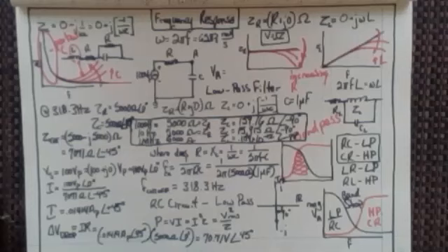Now we could break that up too. You're probably thinking to yourself, well, I can already see that at 45 degrees, if I wanted to turn this back into a complex number, rectilinear, a plus jb notation, that I really only have to multiply 70.71 times the cosine of 45 degrees, which, by the way, is 0.7071. So 0.7071 of 70, doesn't that give me 50? That's right. 50 volts plus J 50 volts. That's what we get. So that's my voltage drop.